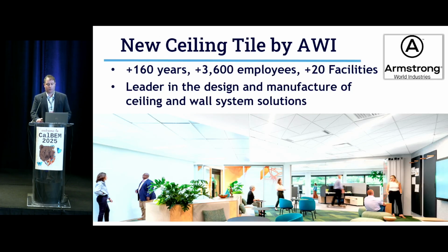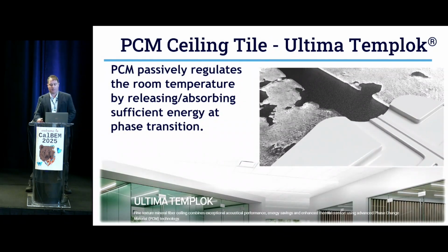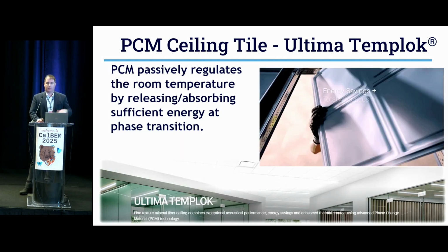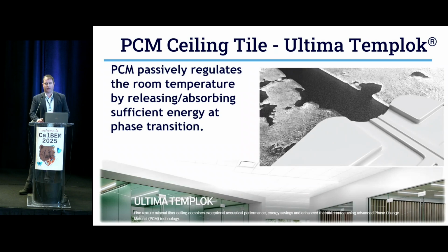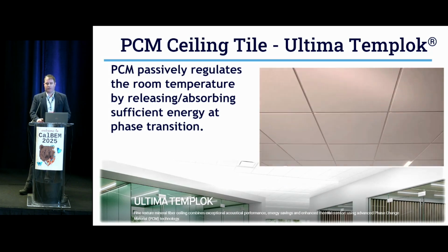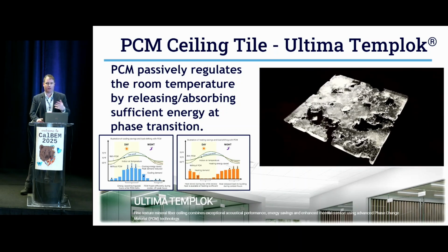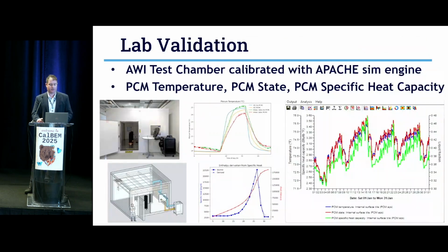Bringing that to a real-world concept with Armstrong, they are the leader in design and manufacture of ceiling and wall system solutions, and have been around for 160 years. There are lots of these, but they, as an example, have a product called Temp Lock, which adds a phase change material to the back of the ceiling tile, or the top of the ceiling tile. It passively regulates the room temperature by releasing and absorbing sufficient energy at phase transition. By phase transition, I mean it's basically changing from solid state to liquid state right when you need it to, when your space set point temperature is changing.